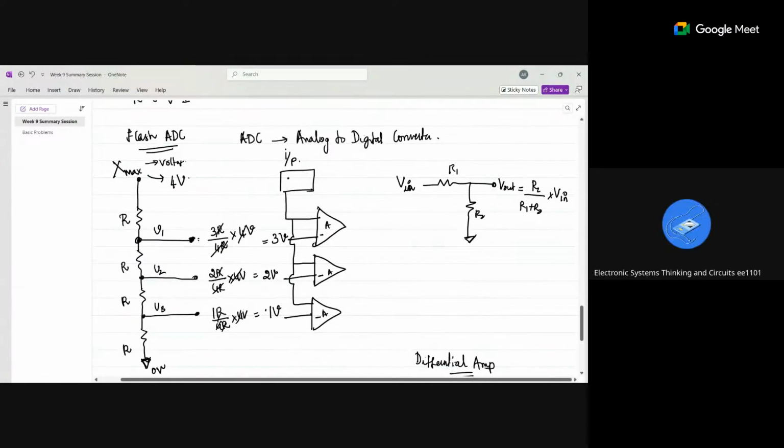Now, as in the lecture, we'll give the same value, 2.75 volt. If I am feeding the input here, I am giving it in the positive terminal, right? Here I am comparing 1 volt and 2.75 volt. So the difference is 1.75 volt, and that 1.75 volt will be amplified many times such that the positive saturation is reached.